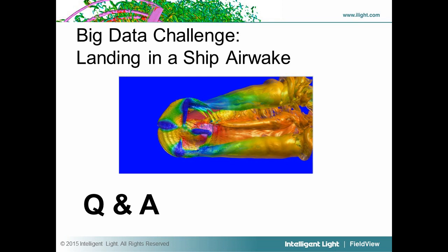So when I'm plotting this in Visit, you'll have your volume mesh, and then you'll have a surface mesh that's separate. And then to tag boundary conditions, Brad recommended that I label each different boundary surface with a different material property. So the material properties I give it are the boundary condition names.